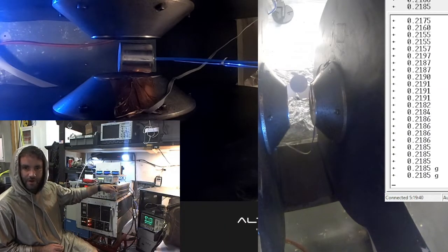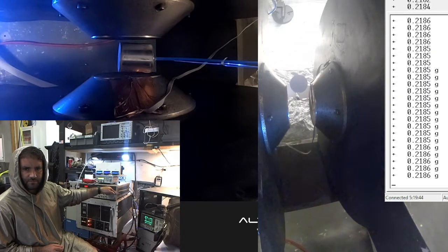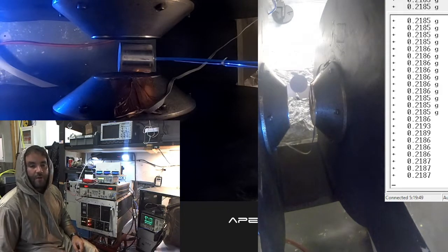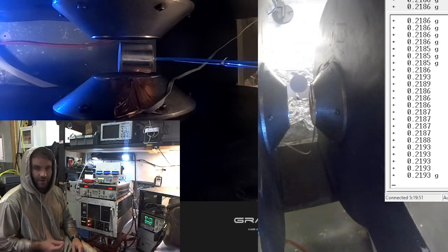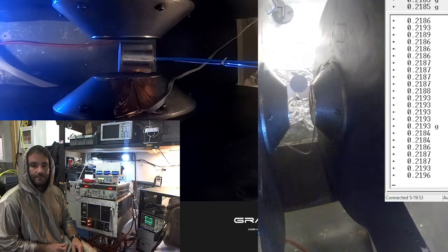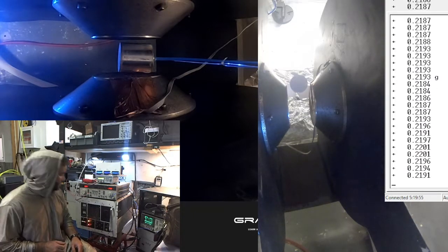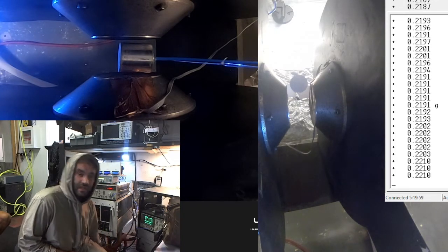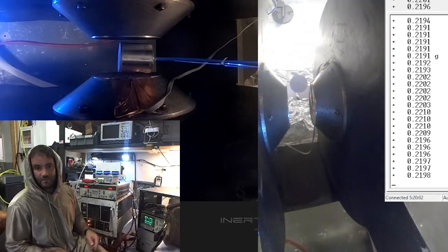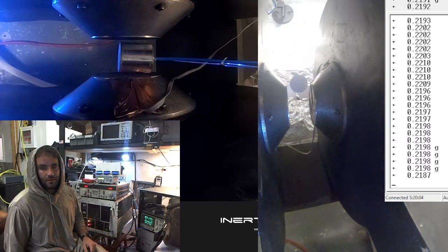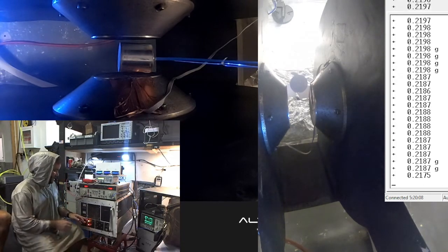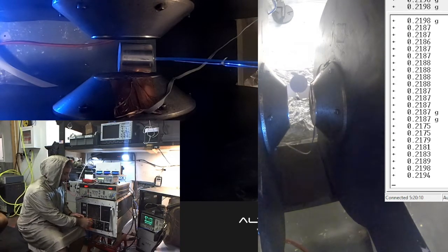About this one over here? Whatever your RF cable feed that goes into the chamber is, I just want you to move the cable from the outside where you're positioned. Destroy everything. You don't want to touch that. You can't move it by a quarter inch or an eighth inch. What I want to eliminate is that your button pressing and your physical motion of the equipment is not messing it up. Imagine that you push on that thing, the cable is so stiff that it somehow conveys that push of a button on the front face.